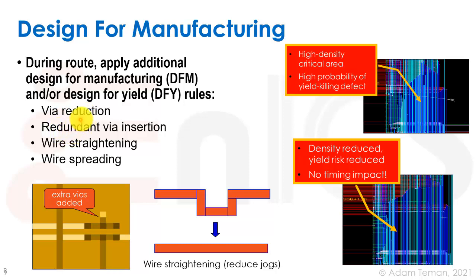On the other hand, if we do have a via, then we want to have as many vias as possible. We want to have an array or a vector of vias. As you can see here, we have this area that needs to go down to this metal over here. Sorry, this one needs to go down to this one. So instead of just putting one via, we'll put a whole bunch of vias. First of all, that will mean that if one of them is no good, the other ones will take its place, and we won't get a short over here.